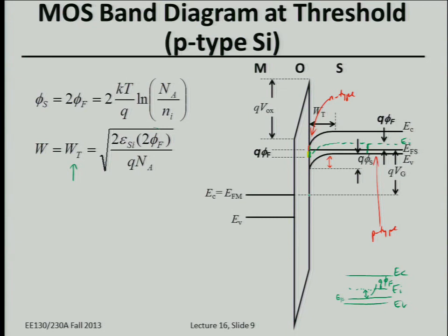Yeah. So the thickness, we'll cover that probably next week. The thickness of this layer of electrons, this inversion layer at the surface, is on the order of 1 to 2 nanometers. So it's very small compared to a typical depletion width. And it depends on the gate voltage: the more positive the gate voltage, the more strongly you're attracting electrons to the surface. So on average, the inversion layer becomes thinner as you increase the gate voltage above the threshold.